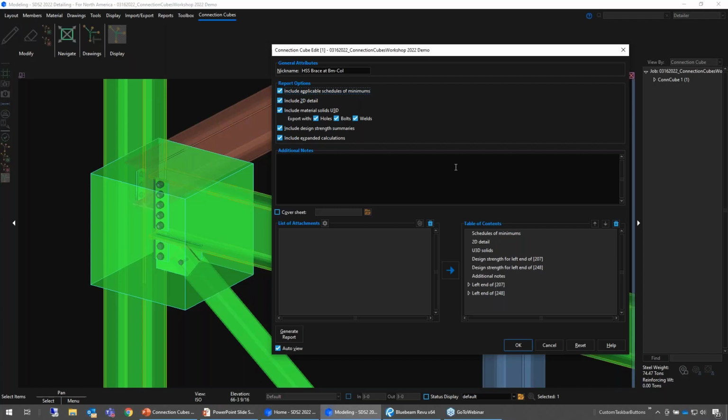Certainly. Yeah, so honestly, we would, of course, lay out the structural steel and then take a look at any of the similar connections like this and try to group them together and design them based on our governing case. At KPFF, we were using spreadsheets and hand calcs. We didn't really utilize a lot of software. Some engineers had that availability, but it was something that I never really felt comfortable with, so I went ahead and did most of it manually. So I would pick something like this, like I know it's going to be a very important structural connection, especially here in California.